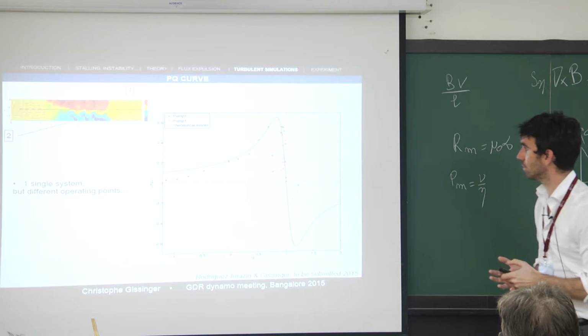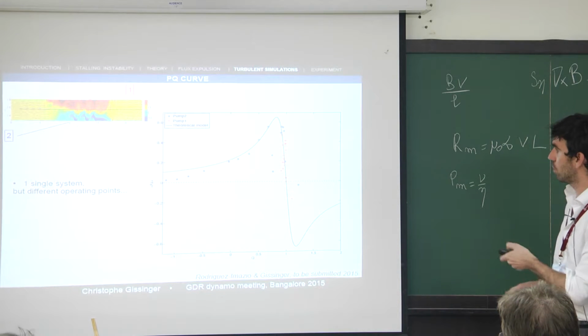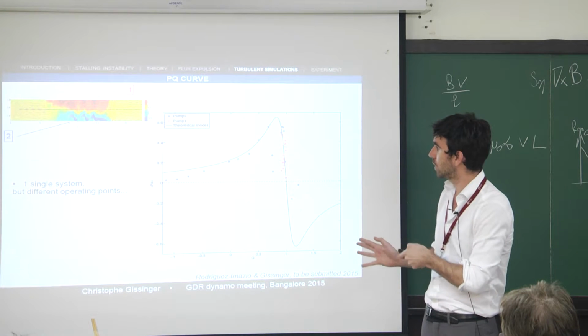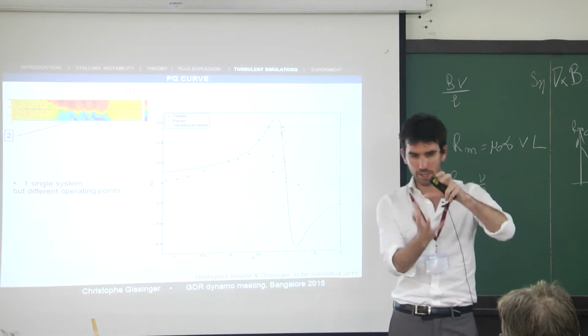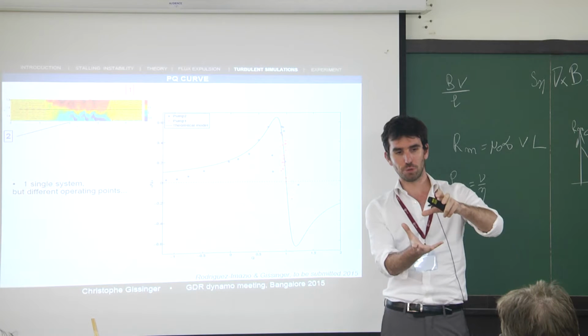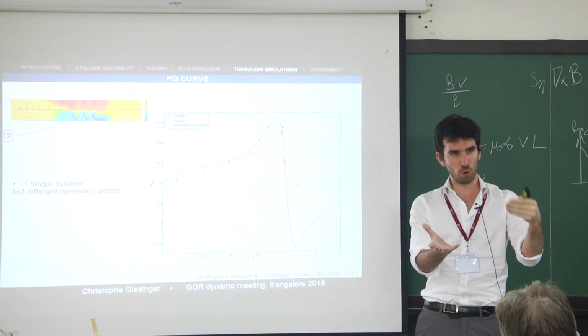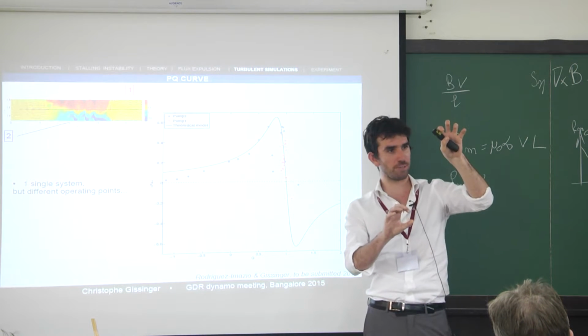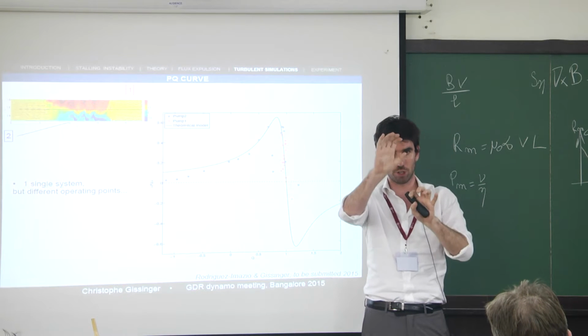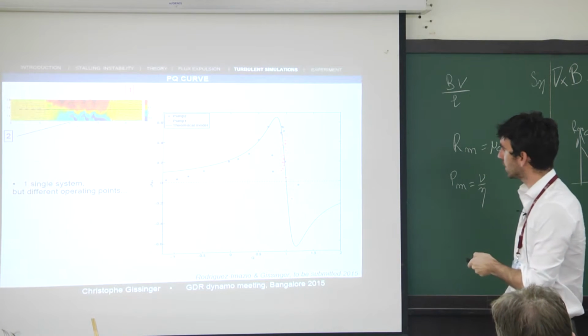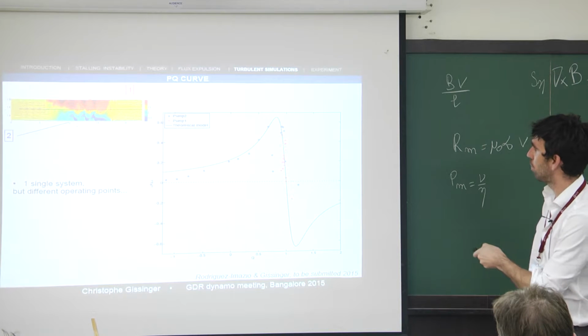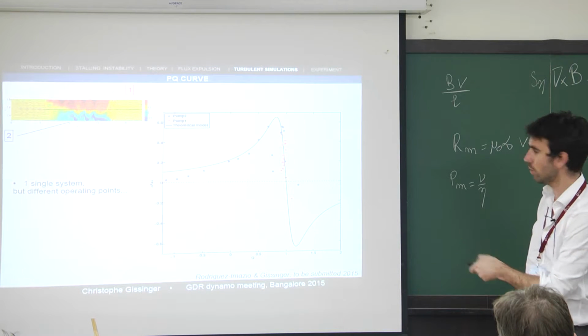Physically, it can be summarized on this curve. To get this curve, I take my pump in a turbulent regime, we impose a flow rate, and we measure the Lorentz force and the flow rate in each individual region. If you do that, you get these dots, and the colors correspond to the two different regions.